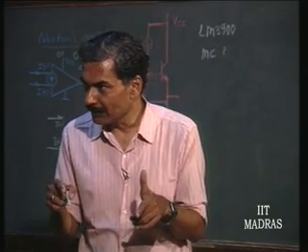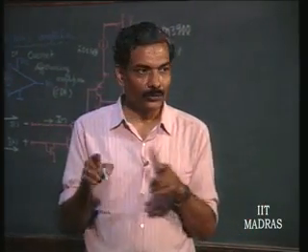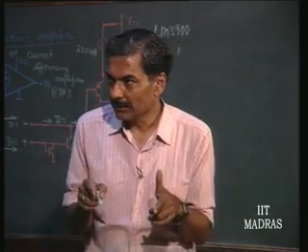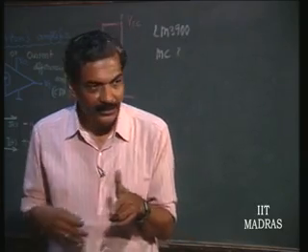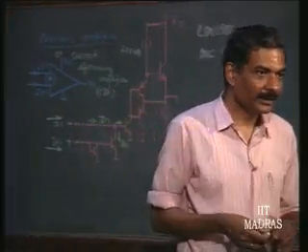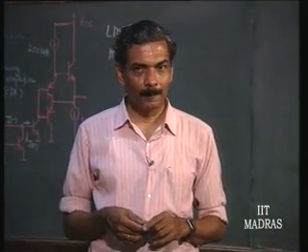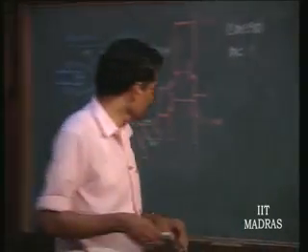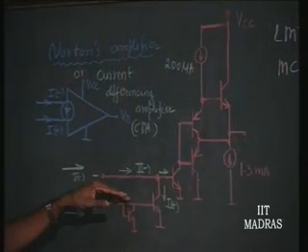In a negative feedback situation, the two input currents should become equal to one another. In the voltage differencing amplifier, if it is used in a negative feedback situation, the two voltages would have become equal if the open loop gain goes towards infinity. Here, if the open loop gain goes towards infinity, the two currents will become equal. Is this point understood?